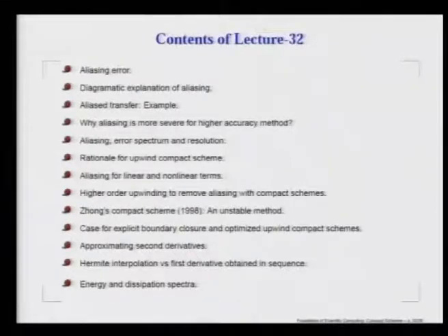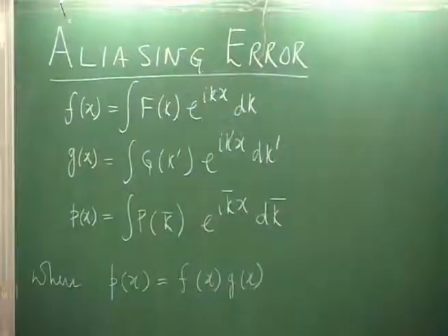We particularly highlight what is required in many simulations: not only must we express the energy content of the system correctly, we must also describe how the dissipation is. While energy may be packed in the lower wave numbers, we know that dissipation keeps increasing with wave number. So, there is a case for uniform resolution of the spectrum to balance, in an equilibrium flow, the energy and dissipation. This is a major issue, and this is a major source of error,